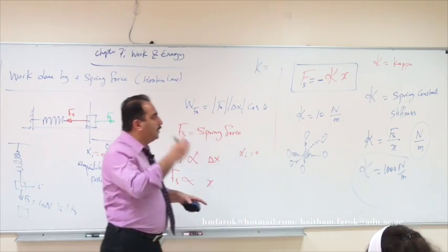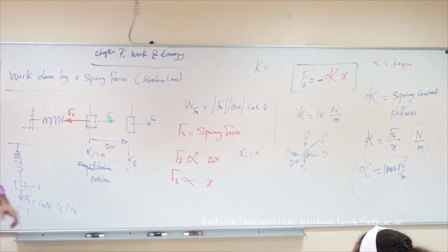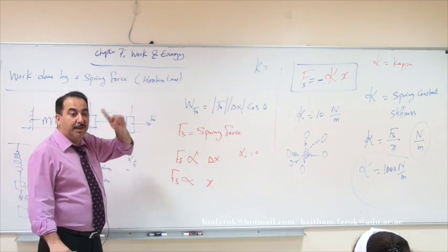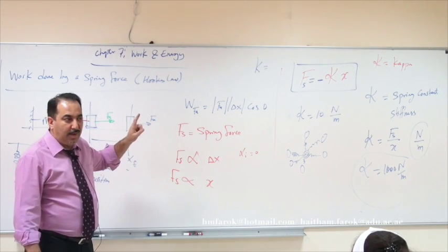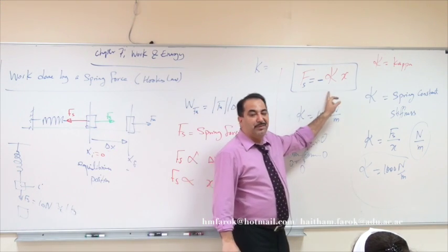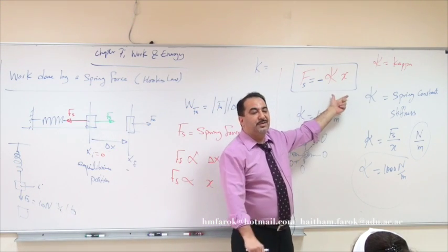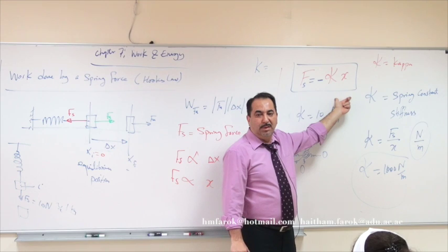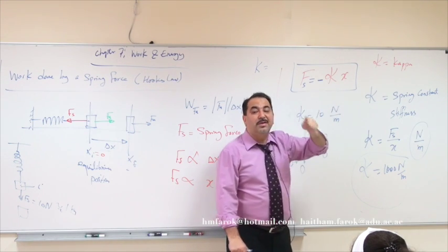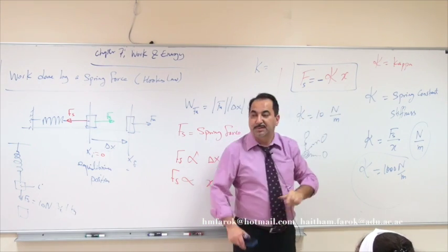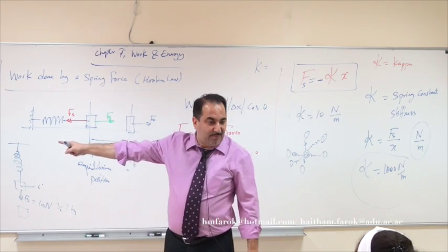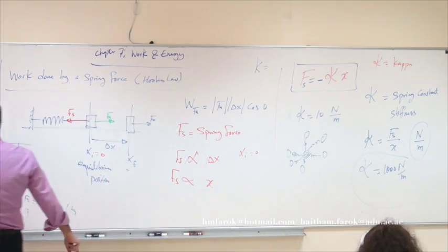Now, what is next? What do we need now? Remember the title says work done by the spring force. What did I do here? I just found the force of the spring. Now, is this force constant or variable? So how do you find the work done by the spring force? You have to integrate the force. So now we'll integrate this force.